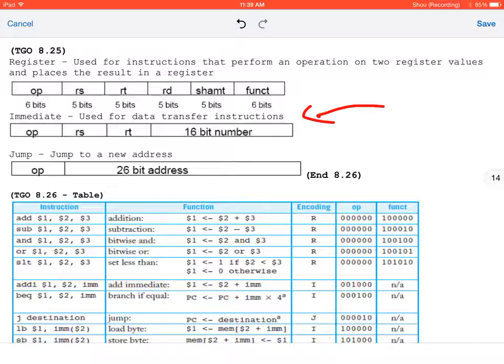So if I'm shifting left by 2 to multiply by 4, what would the shift be if I'm doing an 8-bit data path? So we've done 32, right? We have to get from 32 to 4. We have 4 8-bit blocks for byte addressing, which is why we have to multiply by 4, because a 32-bit value requires 4 8-bit blocks. In an 8-bit data path, we only need 1 block. And shifting left by 2 is the same as multiplying by 4 in decimal. So what would the shift amount be for an 8-bit value?